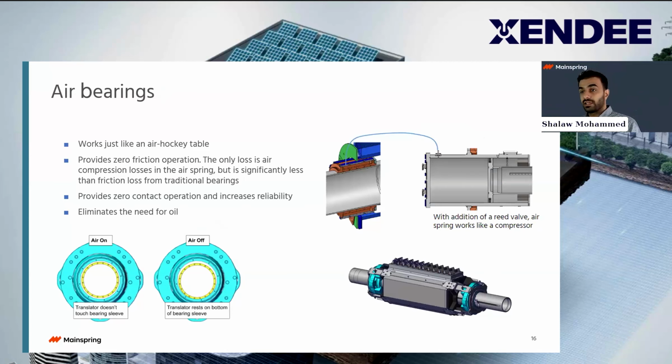Sorry, just one thing about this slide. The elimination of oil also increases the efficiency. Why? Because if you look at a traditional engine, you have the system to manage airflow. You have turbos that push the air through. You have valves that are opening. Because of the valves, you have certain other equipment, and then you also have an oil pump that pumps oil into the system. These are all auxiliary load, so they actually take away from the system capability.